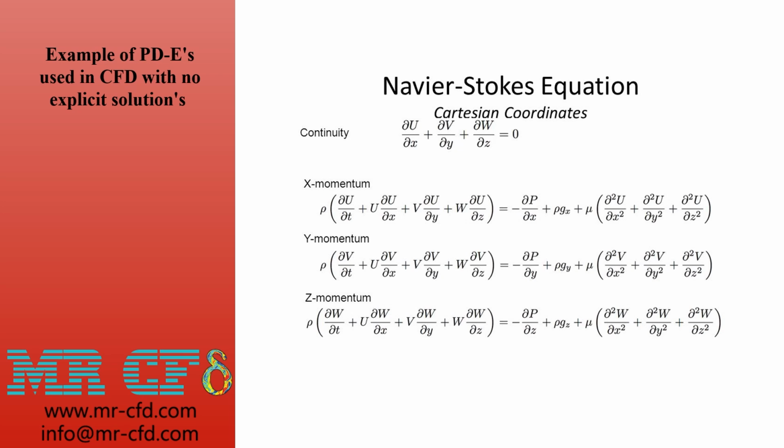So as you know, in CFD we face numerous equations that we want to solve over our objects. These equations are mostly PDEs, such as the Navier-Stokes equation, and there is no exact solution for these kinds of equations. So we need to use numerical methods to calculate the values of these equations in each cell zone, and to do that, we need to generate a mesh grid for this computational process and simulation.